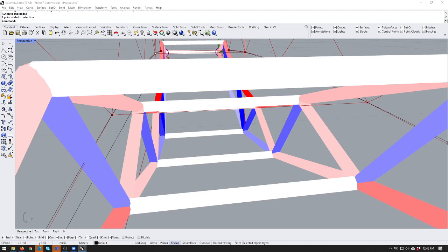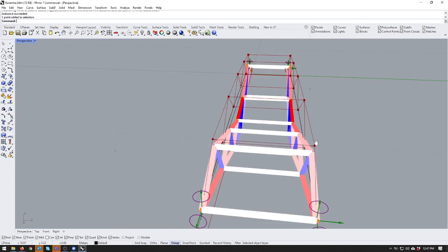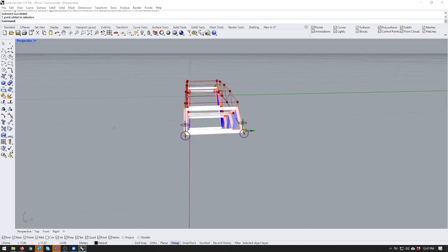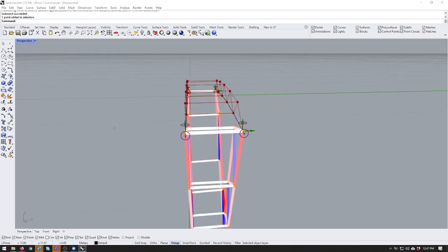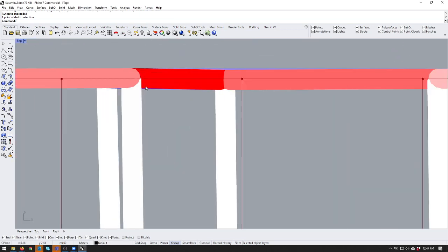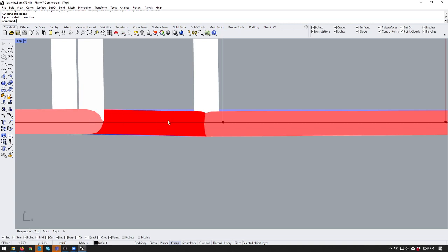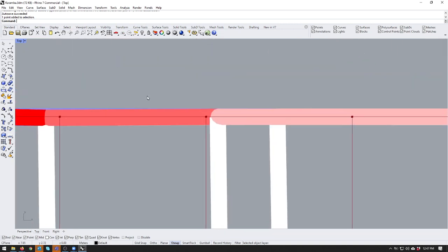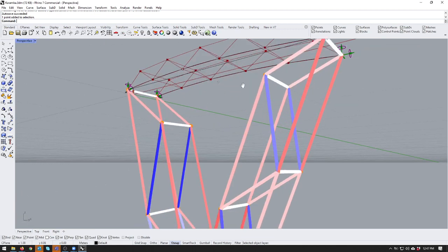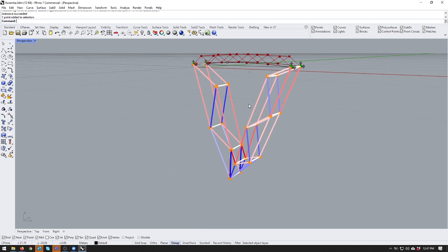and minus 5. No, you can barely see it. It's because there's barely any force there. But yeah, you can see that deforming a bit weirdly now. You can see it sort of skewing off. There's some torsional elements. So try and add some random forces in different directions just to represent the randomness of the real world.